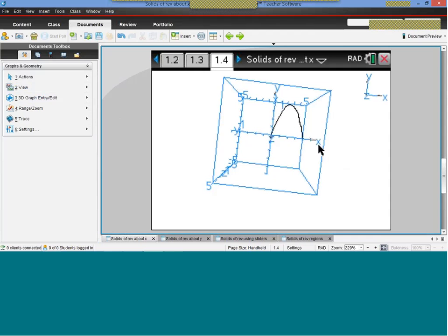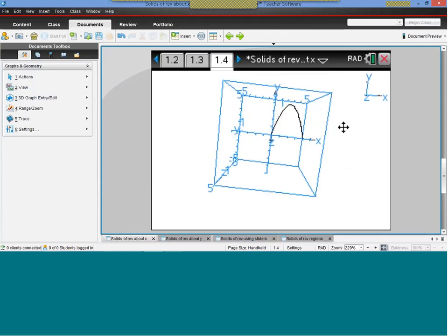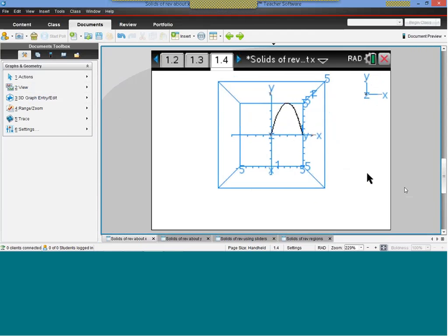I'm just going to reiterate a couple of things that Brian introduced. You can see I can rotate this thing around and look at it from different angles, but one of the good things to be able to do is, if I type Z, then I'm looking along the positive Z-axis. In other words, I'm looking at the XY plane as we are familiar with. If I type X, I don't see much because I'm looking along the positive X-axis and I can just see a line there. If I look at Y, I see even less. So let's go back to the Z and look along the Z-axis and see our curve in the XY plane.